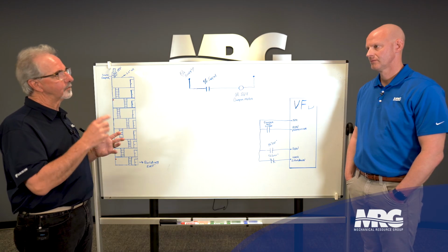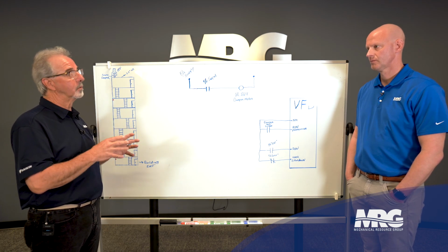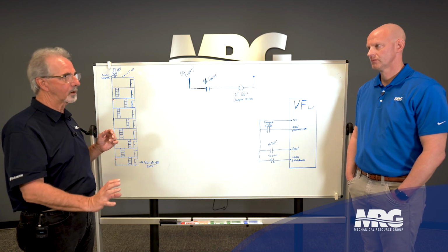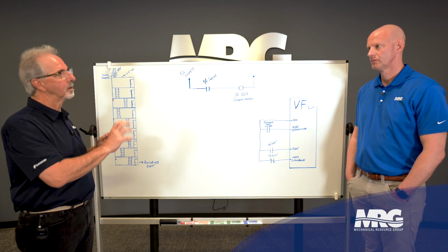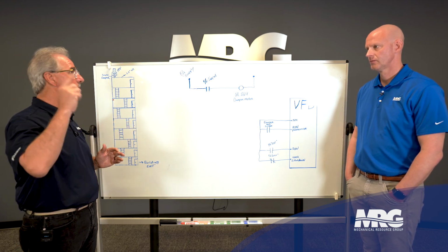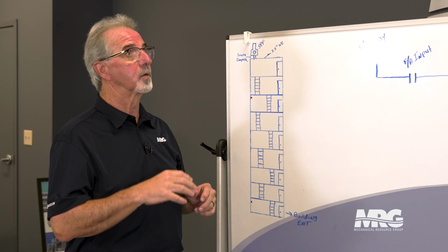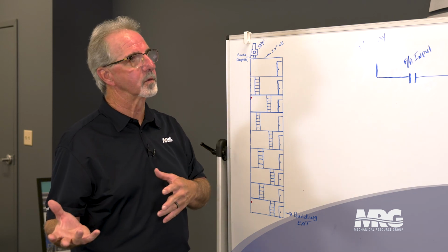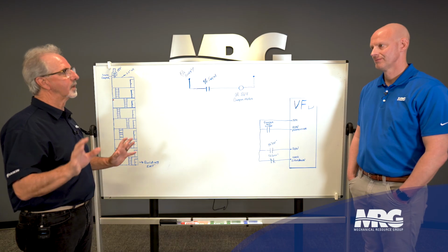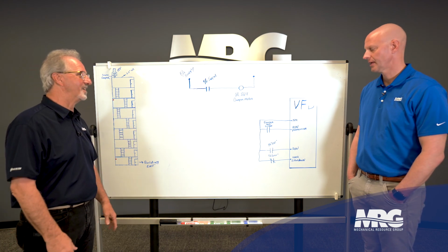So then I know that the fire alarm contractor is probably going to be using hand-off-automatic relays that will be wired. It'll be a supervisory control, and it very well could be wired all the way back down to the fire alarm panel, or it could be standalone. And what it is, a hand-off-automatic. He's going to send me a hard contact closure that says, okay, run. And then he sends me another hard contact opening that tells me, hey, stop running. The fire department's come in, they don't want to move, they don't want to pressurize anymore, shut it off. And so they can shut it off without going to the device, because they're not familiar with the building. They don't know where the building's at, you know.